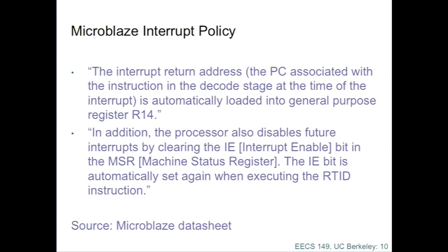Seems bizarre, but nevertheless, that's what they did. So if you're writing a compiler, you need to read these specs very carefully, right? And make sure you don't use R14, because if an interrupt occurs, whatever you put in R14 is going to get obliterated, all right? Unless the hardware also pushes it onto the stack before doing this, which might be stated somewhere in the manual.